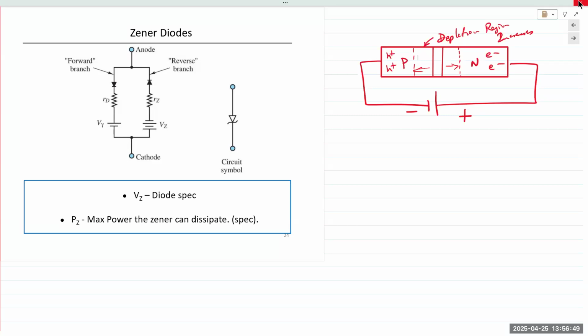And as soon as they move out, if they are within the depletion region, they are immediately attracted. So if they are within this region right here, the excess charge carriers generated due to, let's say, Vs in reverse bias. These electrons, if they're within that, they are minority carriers. There are holes on the other side. They are swept away. They come under the influence of the external field, and they pass through the junction.